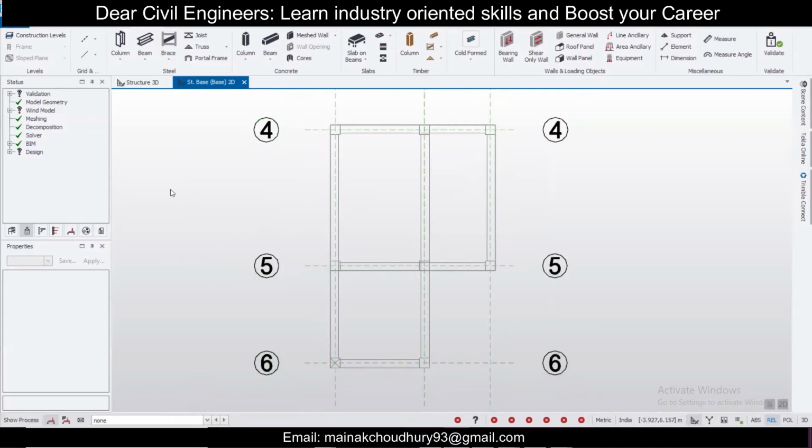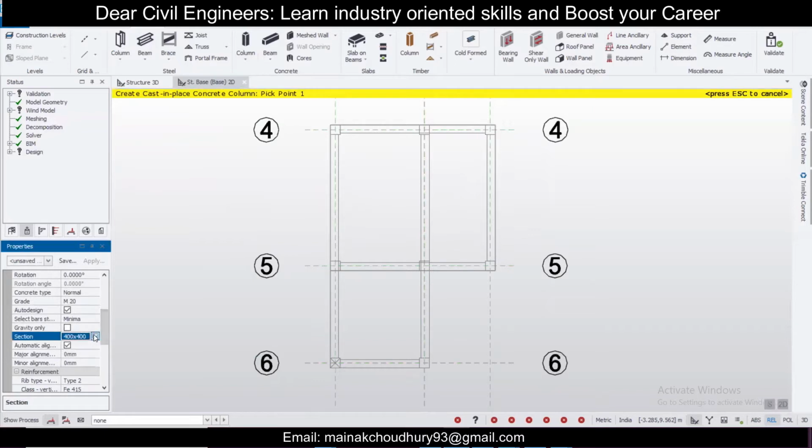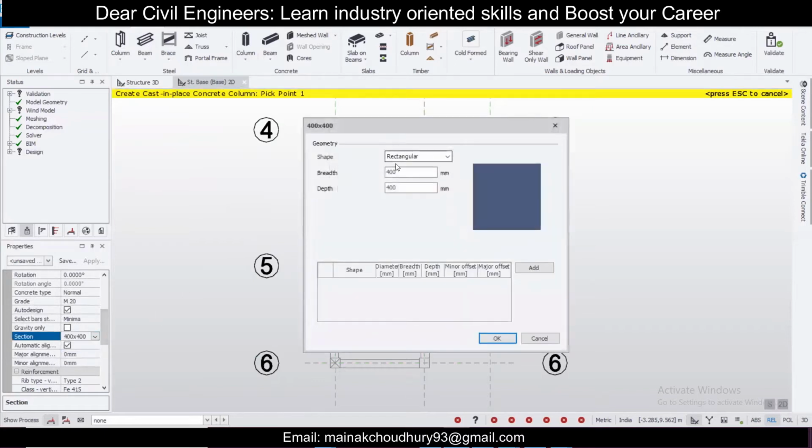First of all, we'll need to place the columns. Select the columns here, and we will set some properties. As you can see, there is no property selected. So first of all, let's go here, and there's M20 concrete. The column size which we want to give is 300 by 300, and let's see whether it will pass or not. If it doesn't pass, then we can increase it anyway.